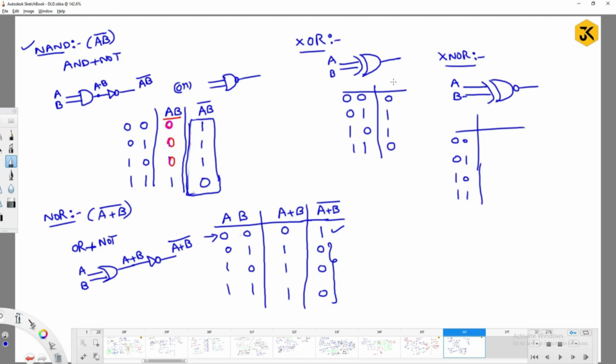What is it like for XOR gate? See, observe here. So what is the resultant? You are going to get this one, right? So basically, the result is 0 1 1 0. What is the complement of this XOR? We get XNOR: 1 0 0 1. This is the equivalent value you are going to get for XNOR, meaning that when both inputs are same, your result will be high, and in all the remaining cases the result will be 0.